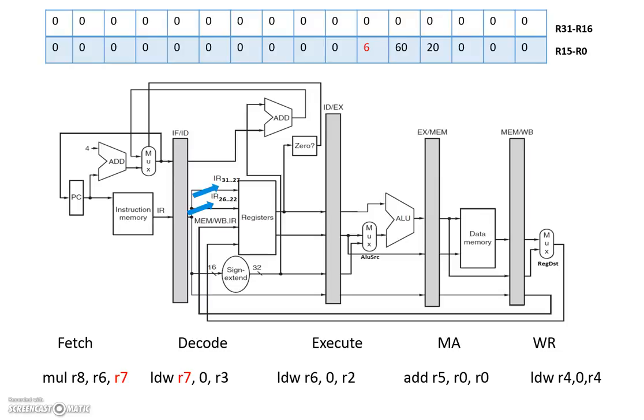But as you can see, the highlighted register R7 is common in both the stages, so stalling must be done. The instructions are passed on to the next stages, but although the previous three stages are inactive, the next stages will remain active as there is no problem of data hazard.